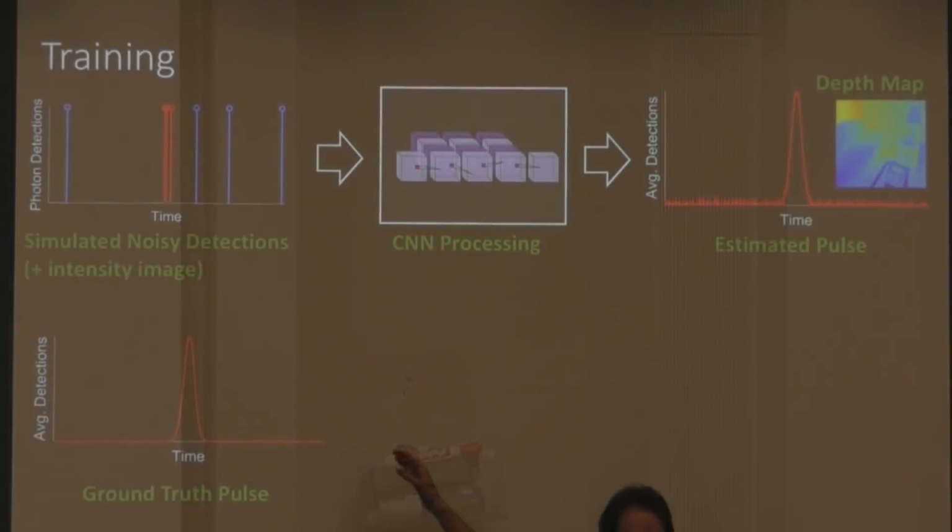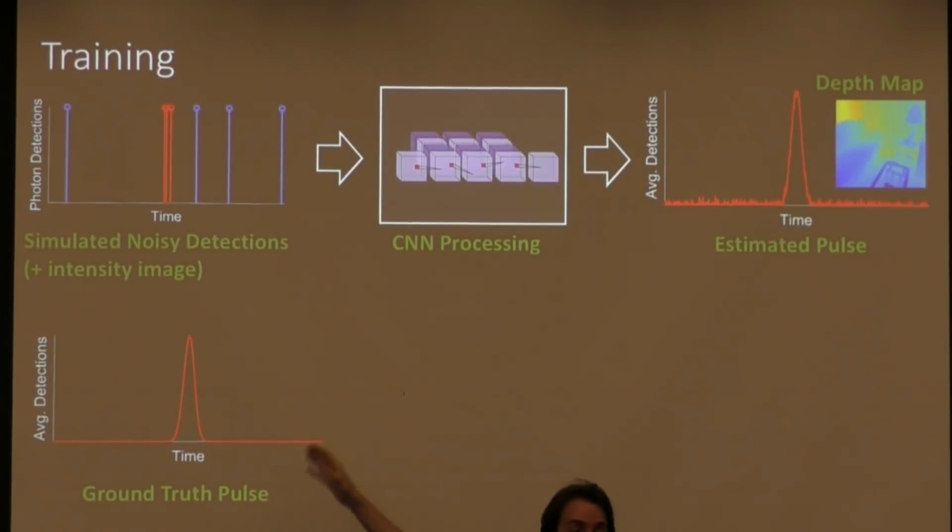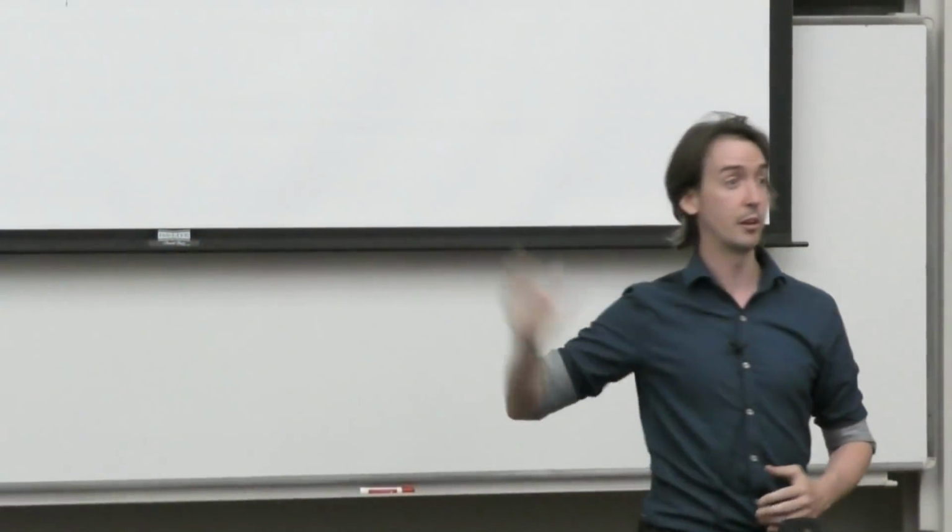The SPAD signal is due to a stochastic process. We take as input a ground truth temporal impulse response, which is basically a probability distribution for when photons are going to arrive at your sensor. You just need to sample this randomly according to that distribution in order to generate your events. That probability distribution function is used for generating your signal.